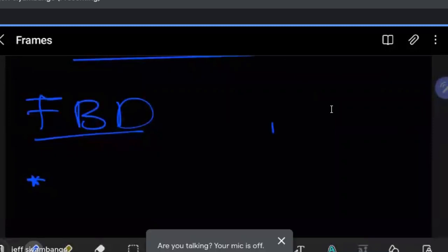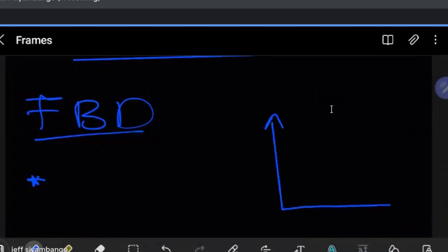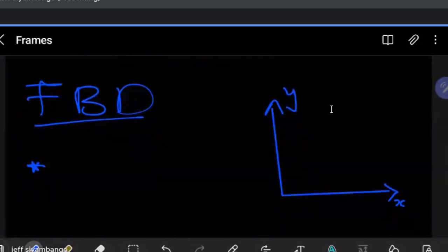For the most part, we'll be taking vertical forces to be in the y, and horizontal forces to be in the x. But you want to pay attention to the question because sometimes they'll just flip them. They can put y here, they can put x there. So pay attention, if such a coordinate system is specified for you, then you have to follow it. If it is in 3D, of course, that's a whole different ballgame. Okay, that's step one. So step one, isolate the members and draw each part.